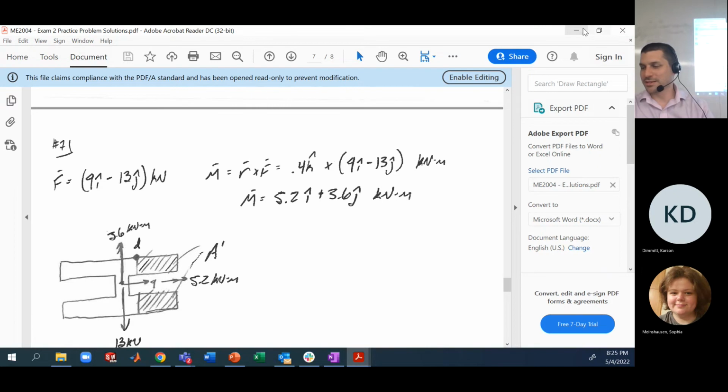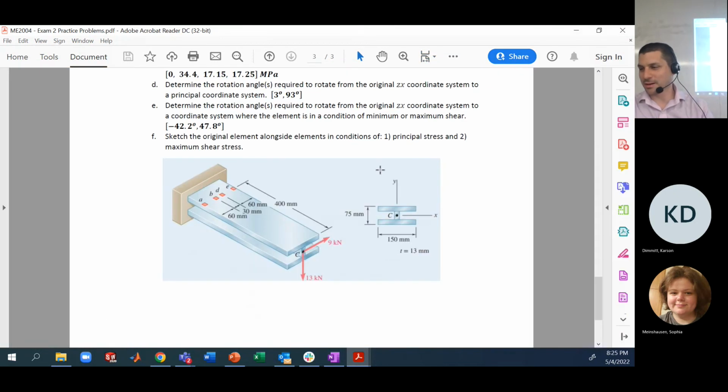The Z direction is the long axis of the bar. So here we're looking at the XY plane, which is the cross section. So Z is coming out of the board at us. We don't have any forces in the Z direction, so we don't have any axial loading in Z. The only possible normal stress that we could develop is normal stress from bending. Got it?